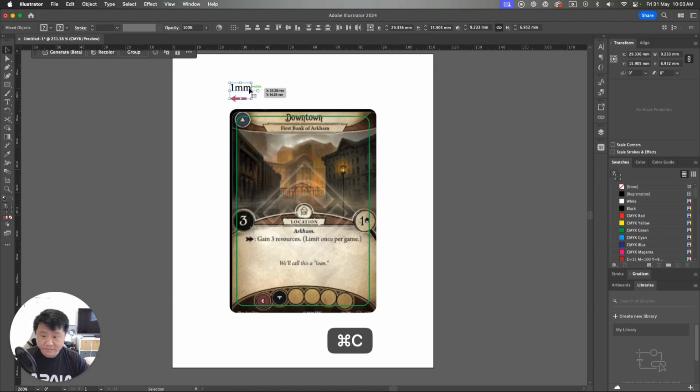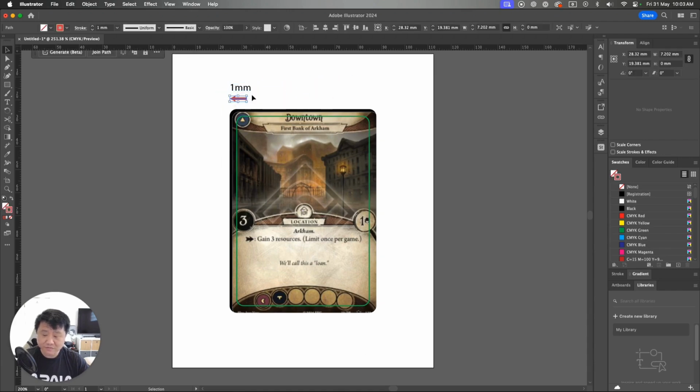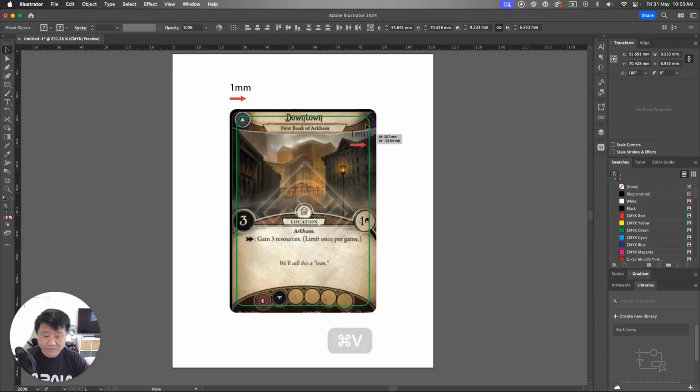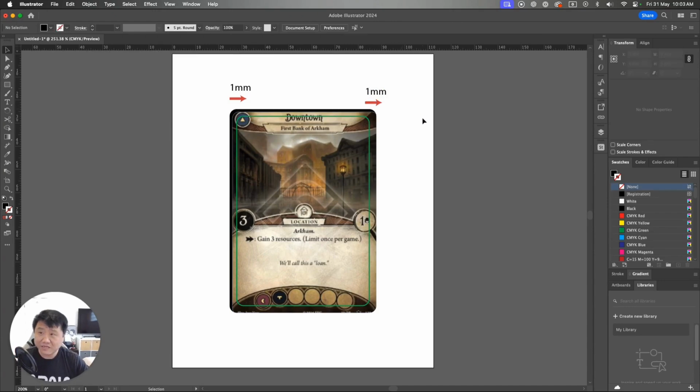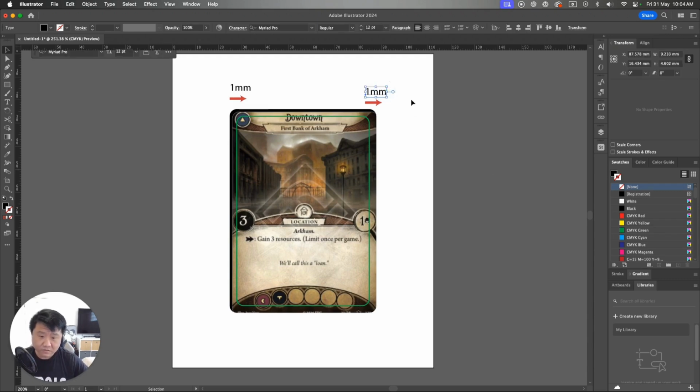The compounding effect is the fact that the arrows depend on your perspective, but let's talk about it from the perspective of the artwork. The artwork has drifted this way, and there's also a mil drift this way, so it has collectively a 2 mil effect, if you will, because you're now seeing a mil's worth of visual element that is not supposed to be seen, and then there's another mil that's been cut away. And this happens in both axes, x-axis and y-axis. So it has a pretty significant effect, even at a 1 mil tolerance.